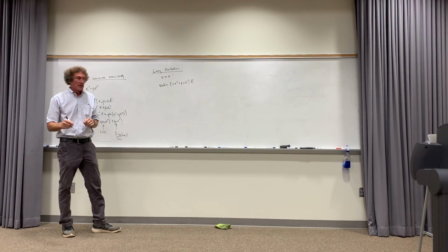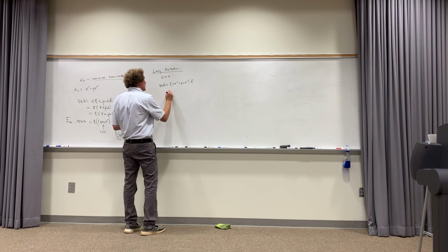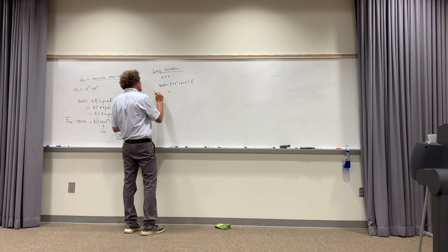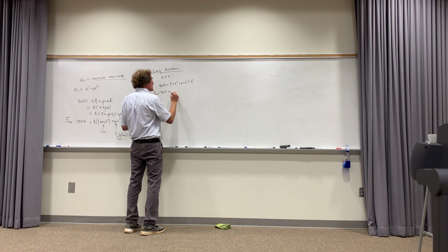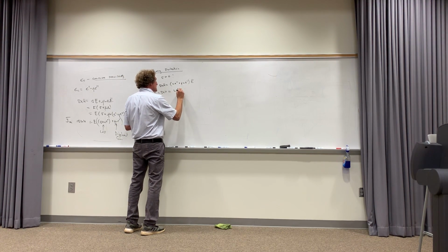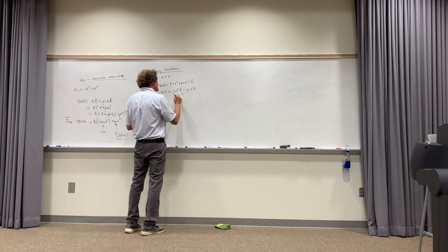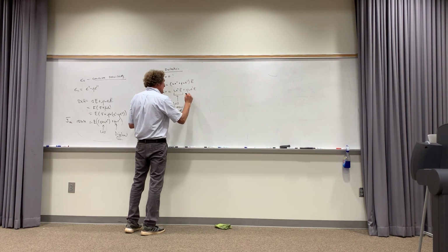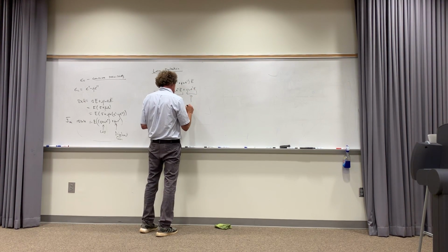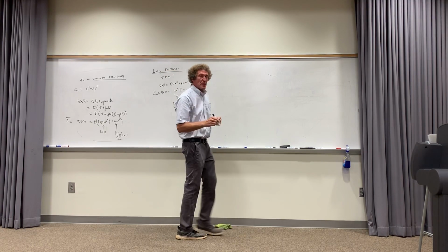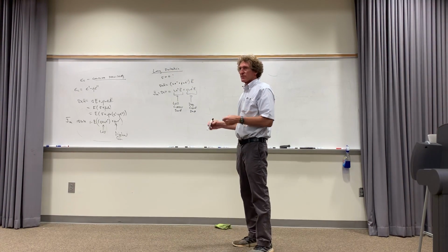Do you all follow me? I'll break them out a little further. I'm going to have what I'm going to call the Maxwell current density, which is going to be omega epsilon double prime times E plus J omega epsilon prime times E. And this is going to be a loss current density. And this is really displacement. Now, this is important, what I'm about to show you. This is just getting familiar with things.